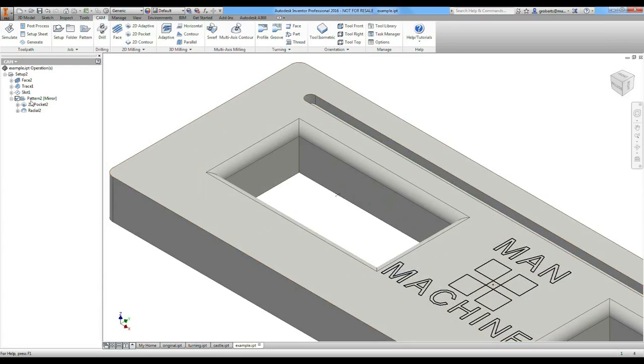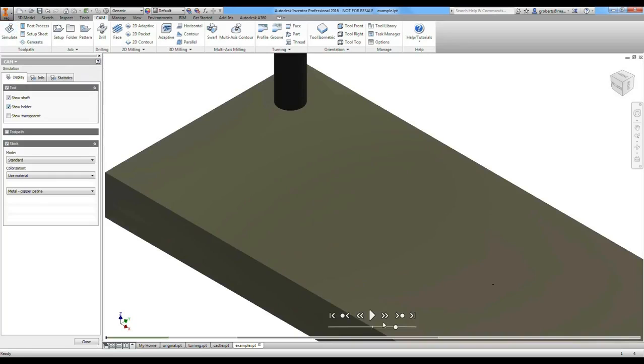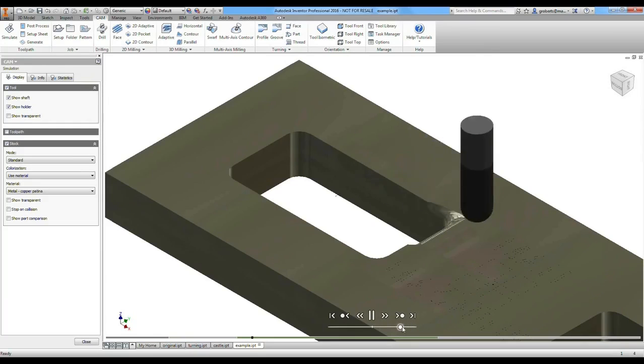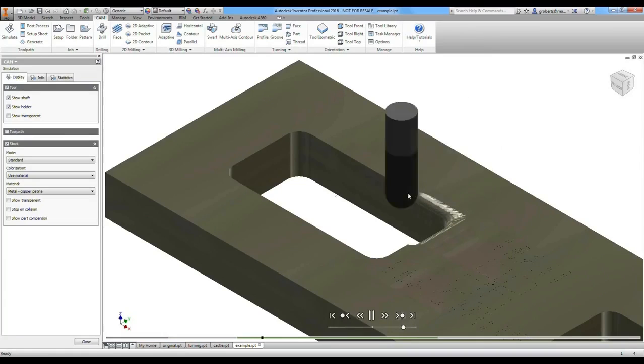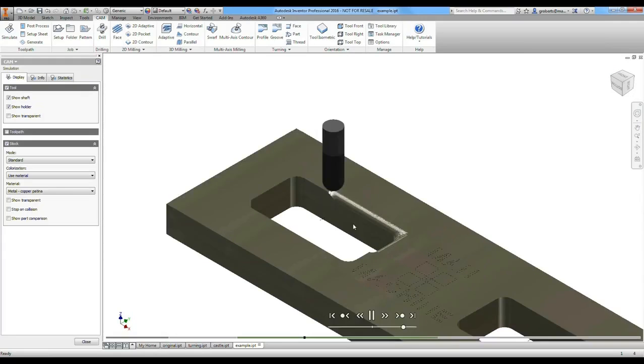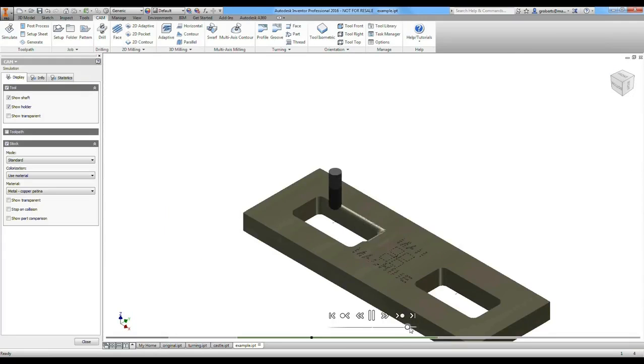So we'll simulate that pattern. Just do quickly the pockets, and then you can see the radial toolpath. It just spirals around, going in and out about this point that I've selected here, the centre of the square, and you can see the centre points here. This is a good way to finish off radiuses or fillets that you put on your file.